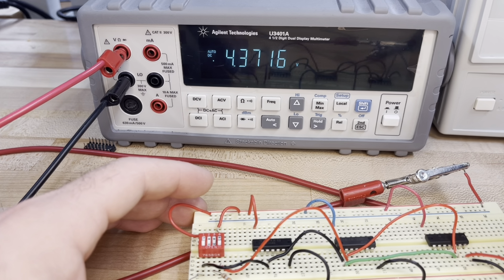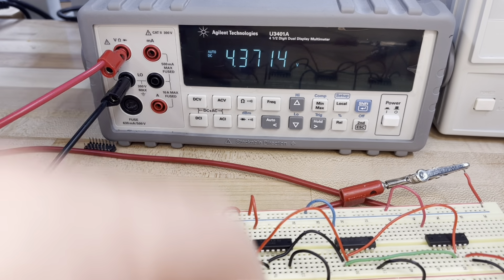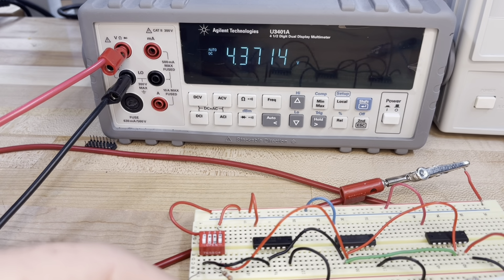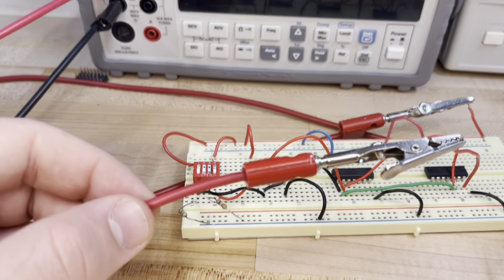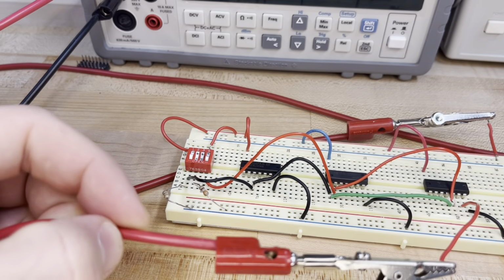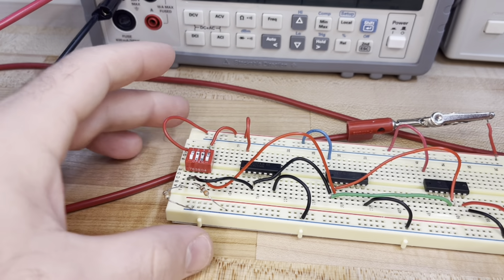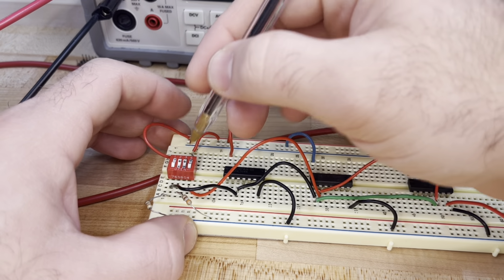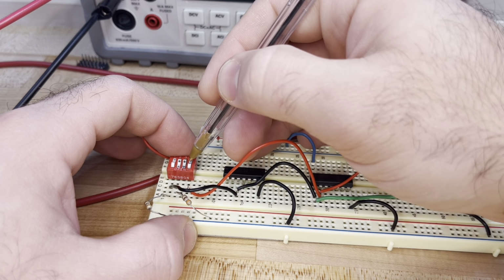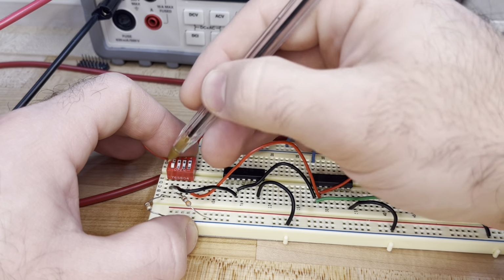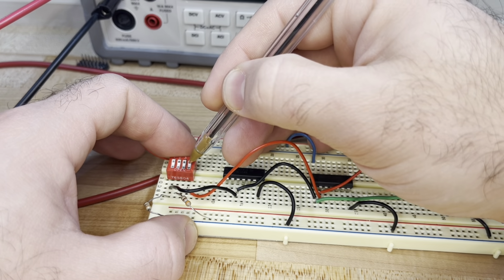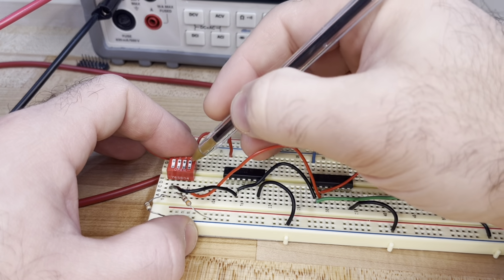For the OR gate, we use pin number 4 and 5. So the output gonna be on pin number 6. As you can see here, I plug it to pin number 6. Then same way, you go to the switches, change them to the proper positions, and then you're gonna get the results and fill the table.